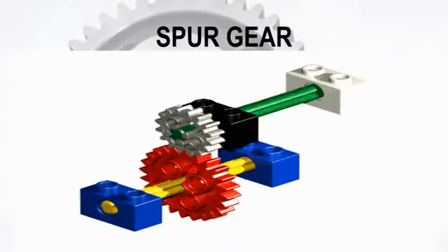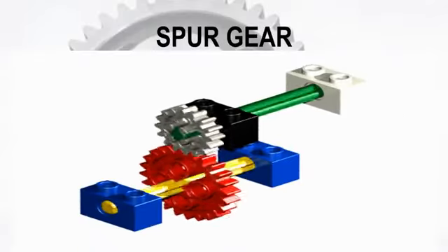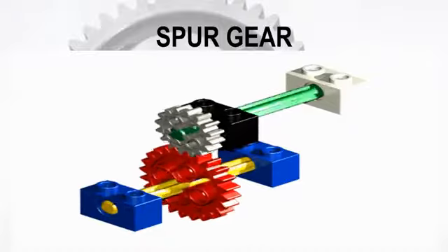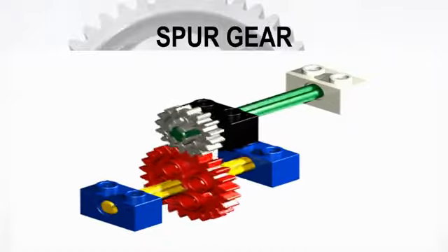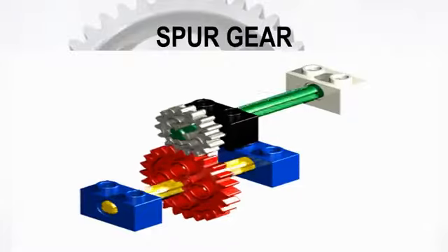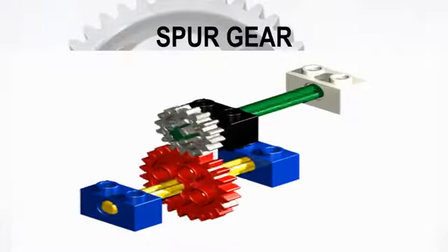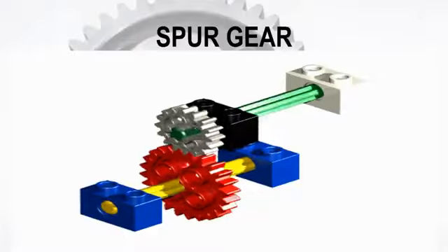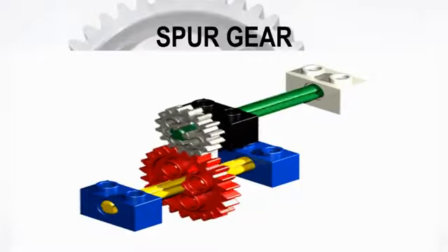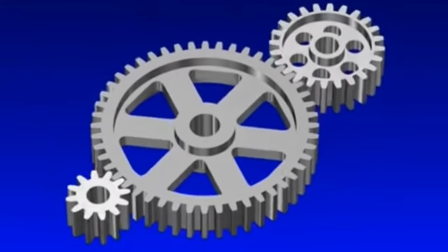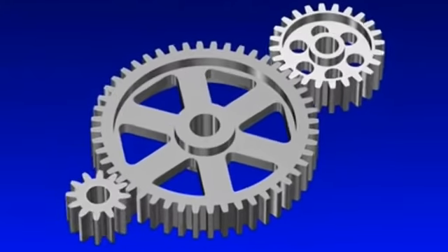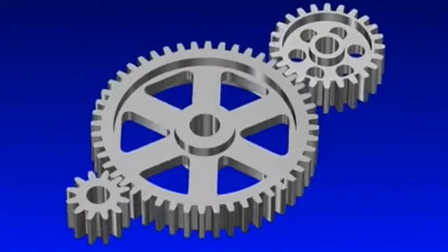Number 1. Spur gear. Gears having cylindrical pitch surfaces are called cylindrical gears. Spur gears belong to the parallel shaft gear group and are cylindrical gears with a tooth line which is straight and parallel to the shaft. Spur gears are the most widely used gears that can achieve high accuracy with relatively easy production processes. They have the characteristic of having no load in the axial direction, thrust load.